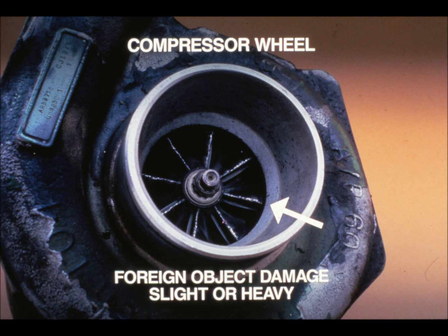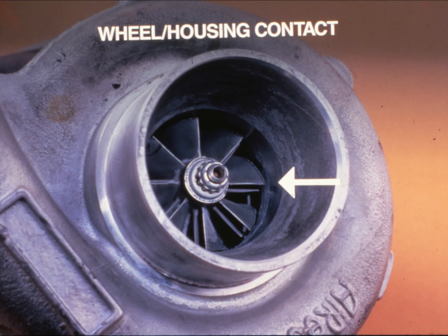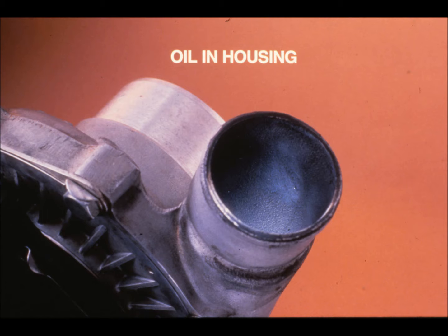3 basic failures are associated with the compressor wheel and housing assembly. Foreign object damage is a primary failure mode and is easily identified. Any damage to the fins, even small nicks, will result in an unbalanced turbocharger and eventual failure. Wheel contact with the housing is the second failure mode. This secondary failure occurs because of a bearing failure, an out-of-balance failure, or other similar failure that results in excessive shaft movement.